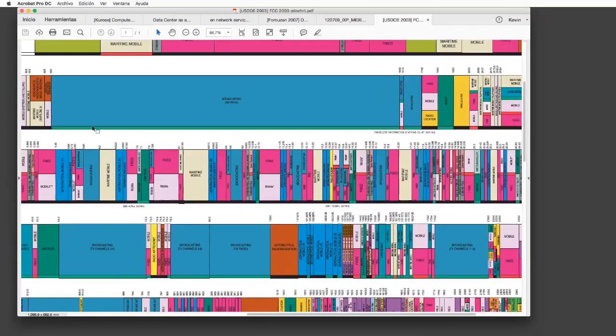So is this a lower frequency or a higher frequency than the rows below? Lower. And what's an inherent drawback of trying to communicate with lower frequency spectrum? Data is slower, right? You can't get as much across it. So what about the ability of this signal to make it through lots of common construction material? Like, can you listen to AM radio inside your house?